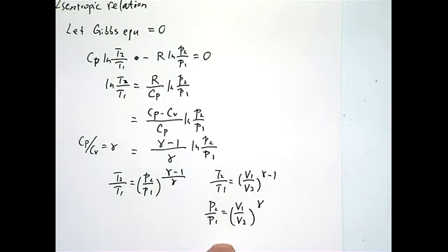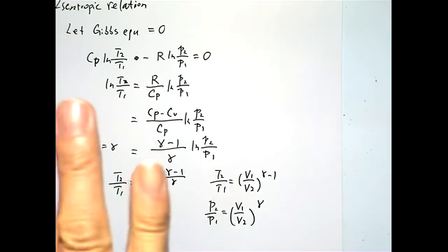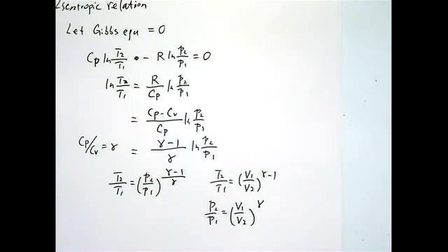And what is the function of this? First, it is applicable to ideal gases, not really applicable to condensed matter, liquid or solid. It describes that if you have an ideal gas going from state 1 to state 2 with an isentropic process, then you will end up with the temperature, pressure, and volume in that relation. It describes from start to end. So that's different from the ideal gas law we typically refer to.